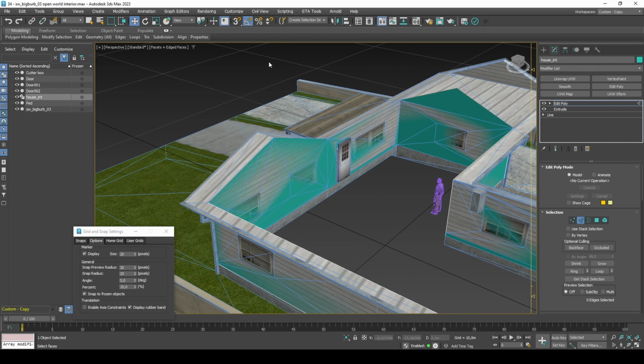At the side of the house near the grass, connect the two vertical edges. With axis constraints, drag the Y-axis of the edge and drop at the corner of the exterior mesh. Select the southern triangle edges and extrude with Shift while dragging. Snap to the edge you created few moments ago. Extrude again and snap at the end of the house.